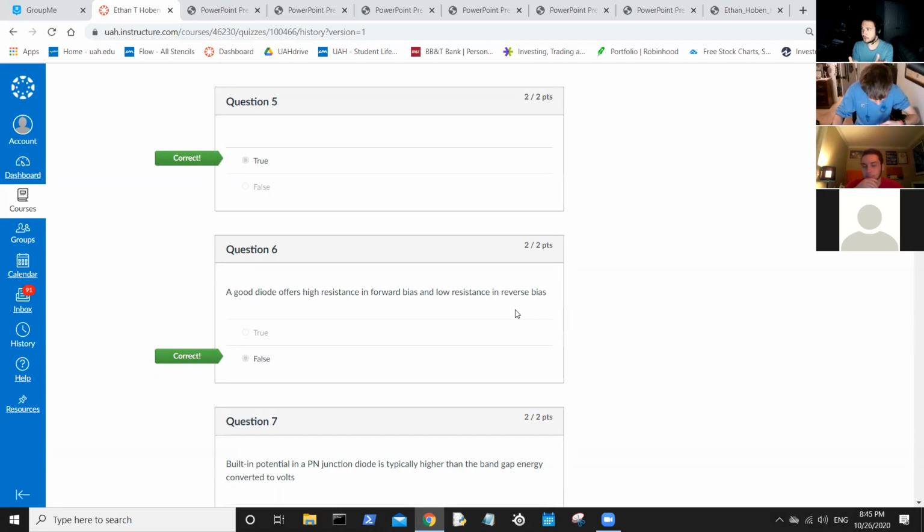It's a polar component. It's what we call these things, like you call an LED a polar component. That's why it's got a cathode and an anode, that kind of stuff. When a polar component exists, it's because either it only really works in one direction, or in some cases, if you backvolt it, it causes it to destroy itself, which is annoying. That sucks. Don't do that.